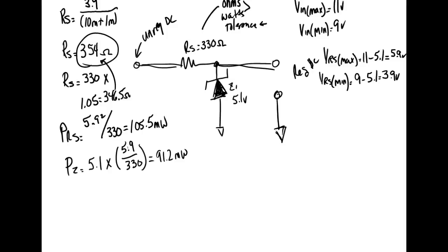And you'll see this done sometimes where you have a regulator chip that regulates unregulated DC, but it needs to be powered up. It's the 723, which is a real nice variable regulator chip. Well, you power it up with a Zener. So you have a little Zener power supply to power the chip on your unregulated side, and then it drives transistors to run your power supply. The LM723, great little chip. It can sense overcurrent. You put a little series drop-in resistor, very low value, on your output, and it'll shut down for overcurrent and over voltage. It's a nice little chip.